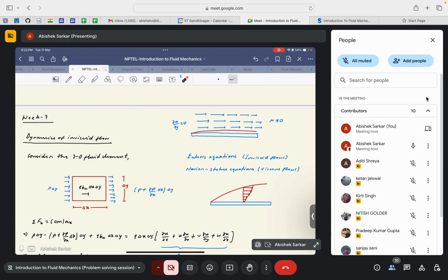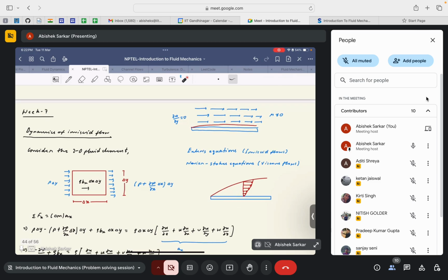it's very important to understand fluid dynamics from the inviscid perspective. First, most of the flow fields that we commonly see around us, the large area of those flow fields, are governed by the inviscid nature of the flow because of the small scale of the boundary layer. The other thing is that since we are neglecting the viscous terms, it helps us reduce the complexity in solving the governing equations.